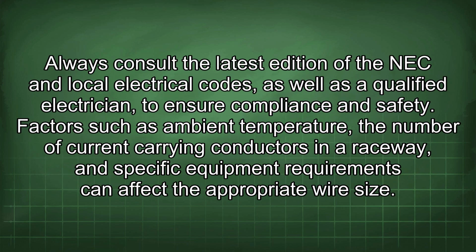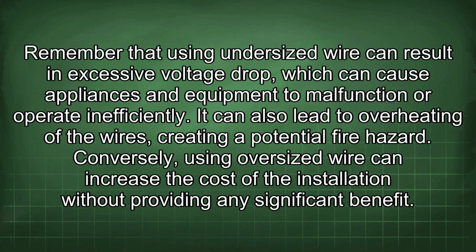Always consult the latest edition of the NEC and local electrical codes, as well as a qualified electrician, to ensure compliance and safety. Factors such as ambient temperature, the number of current carrying conductors in a raceway, and specific equipment requirements can affect the appropriate wire size. Remember that using undersized wire can result in excessive voltage drop, which can cause appliances and equipment to malfunction or operate inefficiently. It can also lead to overheating of the wires, creating a potential fire hazard. Conversely, using oversized wire can increase the cost of the installation without providing any significant benefit.